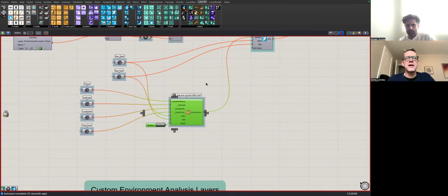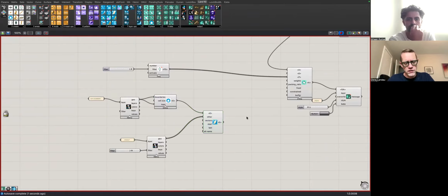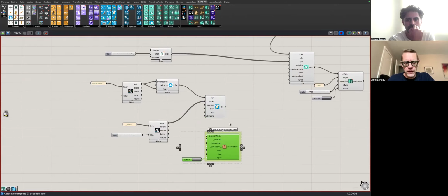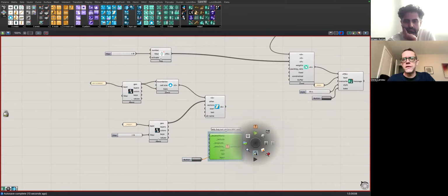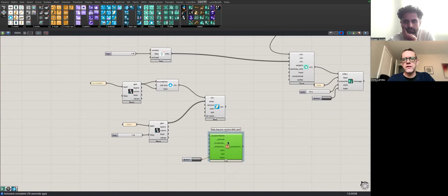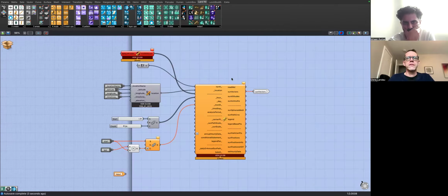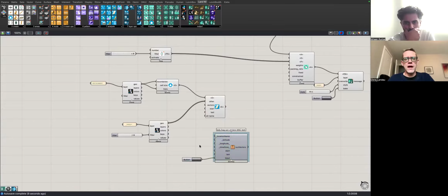So I'm going to take this guy here. I'm going to copy this, and then close that, and paste it right into here. So it's Shift Control or Shift Command Paste V. And I'm going to create vectors based off of a latitude, longitude, time zone, start and last state. This is all based off of Ladybug. So I'm going to hit save, and I need to have a location.